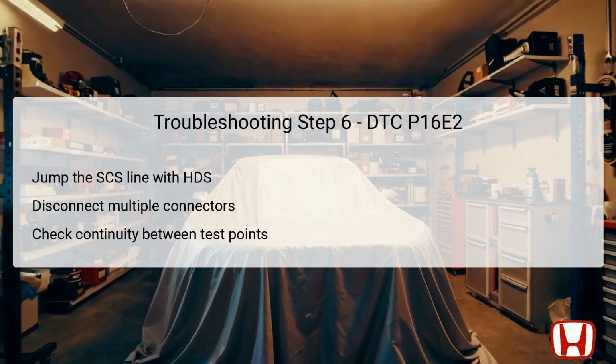At this point, make sure the PCM has the latest software updates. If it does not, you should update it. If issues persist, substituting a known good PCM could provide a definitive solution. If continuity does not exist, it indicates an open in the LIN wire, requiring necessary repairs.